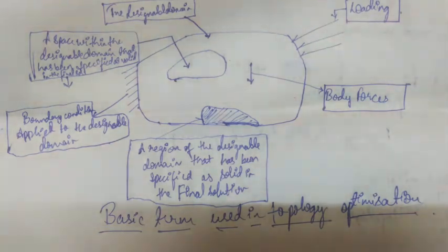ESO has received significant research interest but is generally criticized for being a heuristic technique that does not guarantee convergence to an optimum solution. The SIMP technique is generally accepted in the literature as being the most prevalent tool for the topological optimization of linear elastic structures.